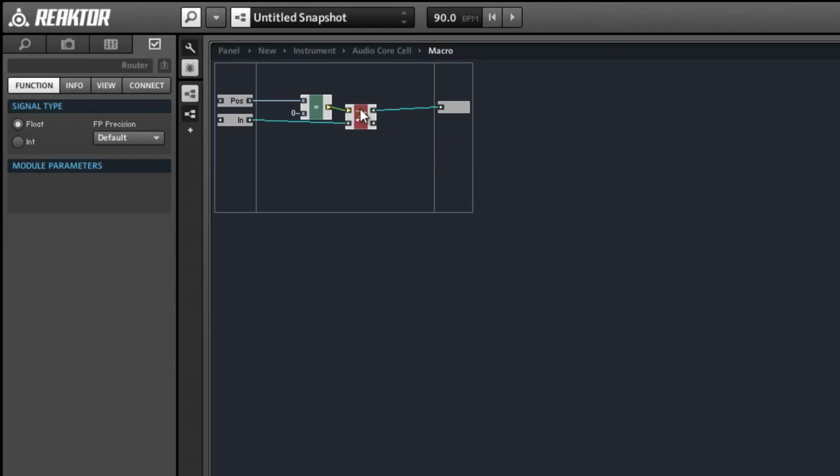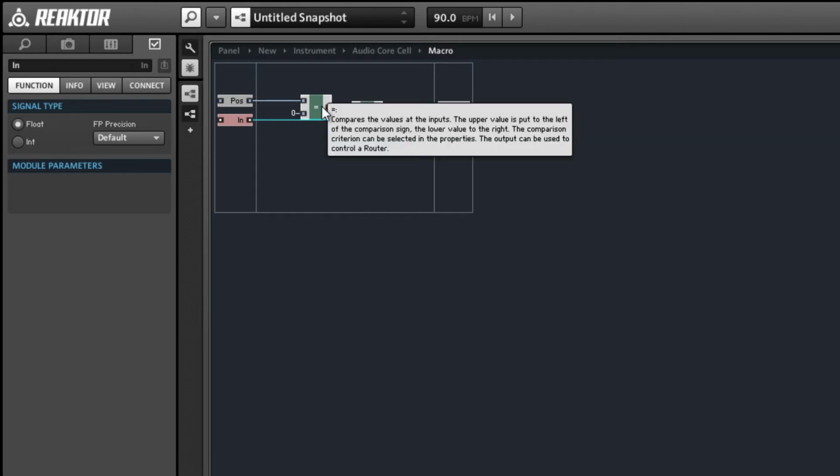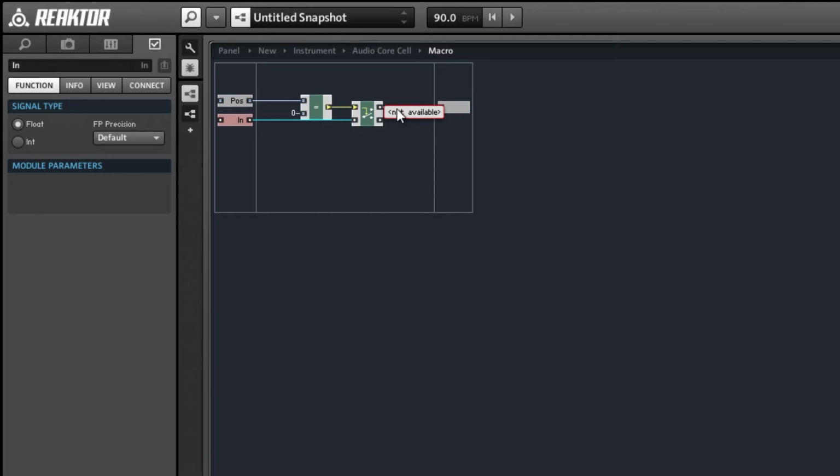And so let's just delete most of it and I'll talk about why. So the way that these routers work is that the compare module is never actually calculated until we receive a value at the input of the router. And when it does, it checks to see what the compare value is equal to before routing the signal. So the way we just had things set up, we were connecting the input directly to all 4 router modules, which meant that all 4 compare values had to be calculated every time we received an input.